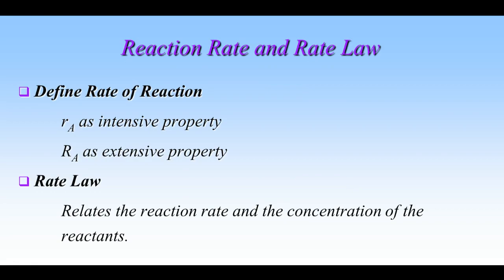Reaction rate and rate law. In this video we will define the rate of reaction and the rate law. The rate of reaction is an intensive property, it does not change with the size of the system, and our reaction term, which will appear in the general mole balance, is an extensive property. And the rate law, which you already know, relates the reaction rate and the concentration of the reactants.